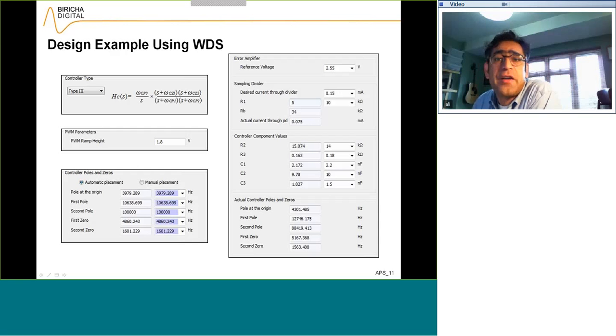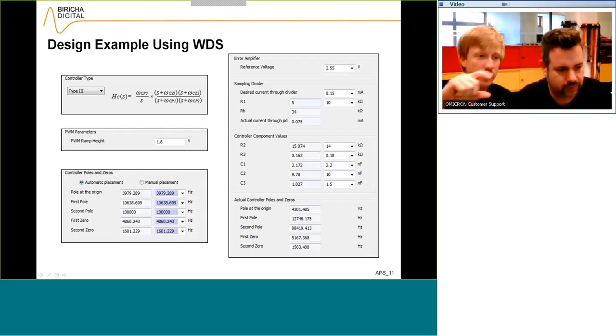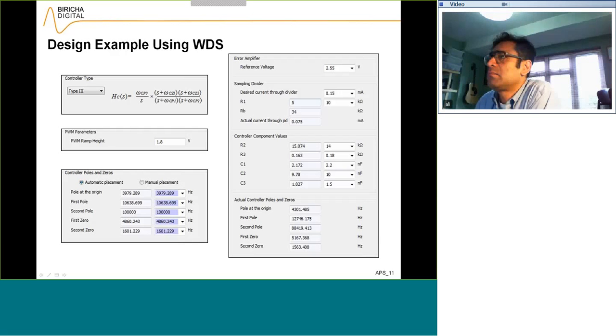So I have got 440 microfarads of electrolytic capacitance, so at the moment I am not worried about the DC bias. In case you're worried, you need to enter the derated value into the software. That's correct, yes. Thank you.